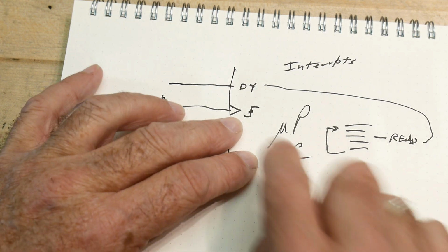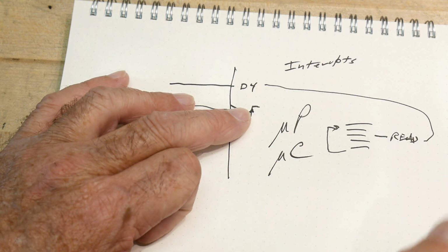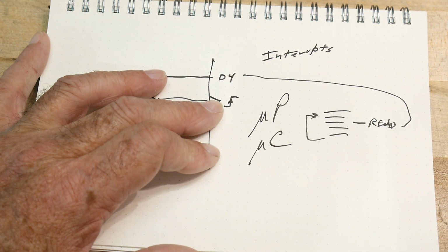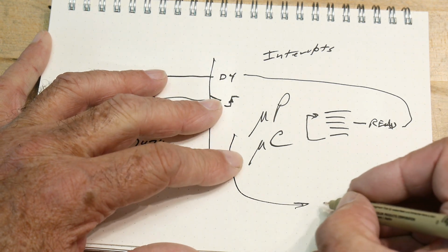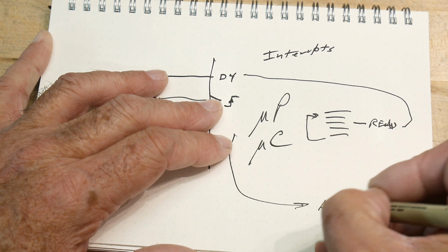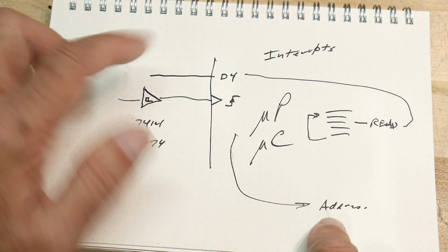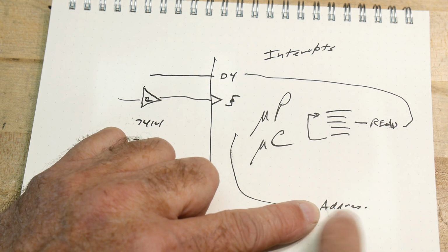So you can make it edge sensitive on the outside and then make this go high and stay high. When an interrupt occurs, there's hardware in the microprocessor that says we're going to do something different. We're going to go over here and look, and usually there's an interrupt address. When this pin gets pulled, it says, jump to this address and do whatever is there.